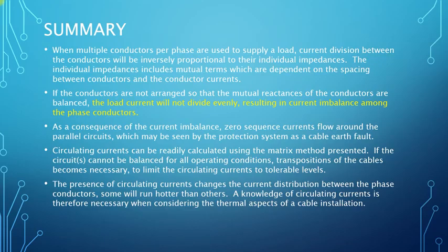Even in systems where the maximum cable earth fault is limited by a neutral earthing impedance, we can still get circulating currents which appear as zero sequence currents, which far exceed the zero sequence current that would be expected during a cable earth fault.